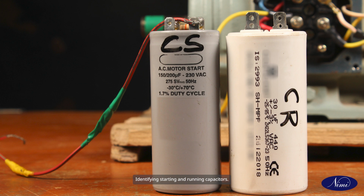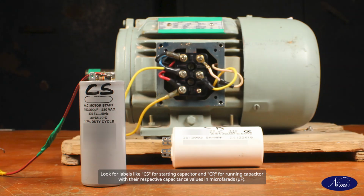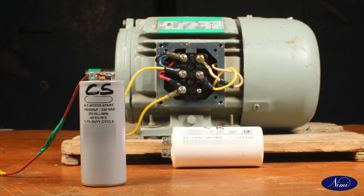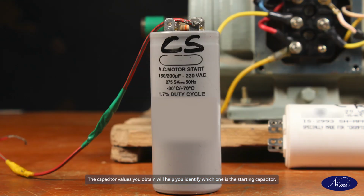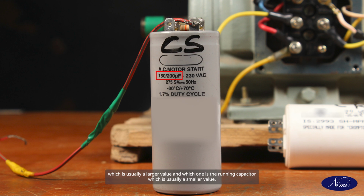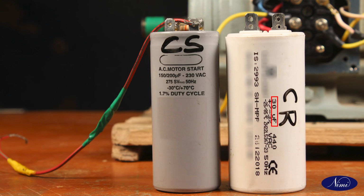Identifying starting and running capacitors. Look for labels like CS for starting capacitor and CR for running capacitor with their respective capacitance values in microfarads. The capacitor values you obtain will help you identify which one is the starting capacitor, which is usually a larger value, and which one is the running capacitor, which is usually a smaller value.